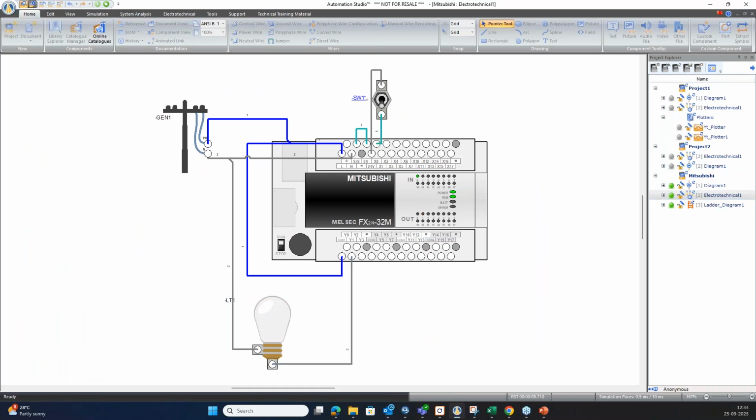So this is how basically you can create your own logic with the help of Mitsubishi. And not only that, but also make one thing sure that the connections that you are giving, like over here, X0, X1, will be digital inputs, and at Y0, Y1 will be your digital outputs. And adding to it, make sure that you have connected the phase wire to the live connection and neutral to neutral. And you just need to make sure that one more thing, that you have shorted this particular circuitry over from over here. So once you do this, your circuit will be in ready condition.